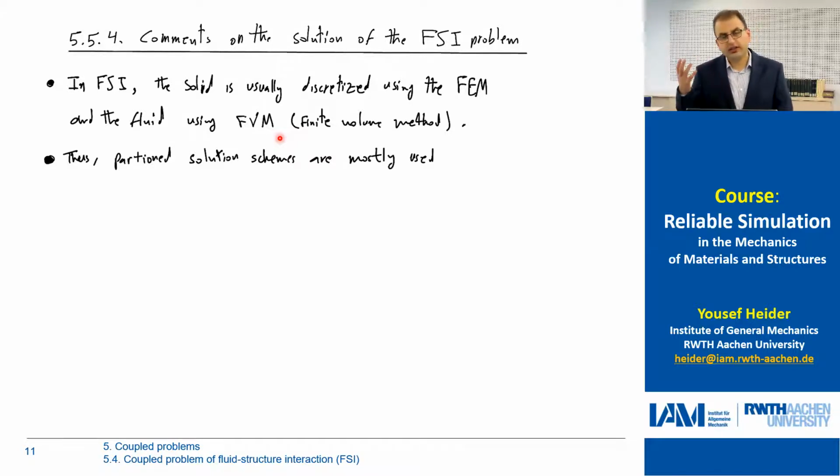And if we use different strategies for the solid and the fluid, then it is easier for us to use these partitioned schemes, because then we solve the solid alone, maybe on a different computer, and the fluid also alone, and then we find this coupling interface. We enforce this at each time step, and then we bring this information from the interface back to the subdomains to update the solution of each subdomain in an iterative way.